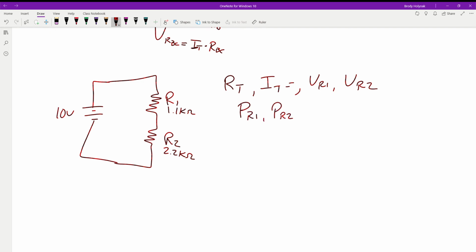One of the things that's very important that we're going to get into is with the power, we need to know how much power is going through this guy, because we need to understand how big of a resistor we need to put in there size-wise to handle it. The ones that you guys have in lab, I believe, are 1/4 watt that came with the kit. I think it says that on the package. That means they can handle up to 250 milliwatts of power. So when you're building a circuit, this is important to know so that we can put the correct size in there. Because if we don't, it's going to burn up, or at least get hot, and it could burn you, even if it doesn't burst into flames.